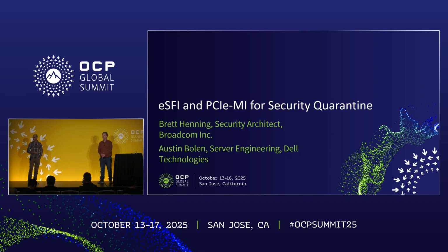Okay, I don't think there are any more questions. I had one. Is this tied to a specific PCIe gen specification? Gen 6, Gen 5? The ECNs were incorporated into the 6.4 specification, but the way the ECNs work is when they're ratified in PCI Express, if you did want to backport those to, say, a Gen 5 switch or root complex, that is allowed.